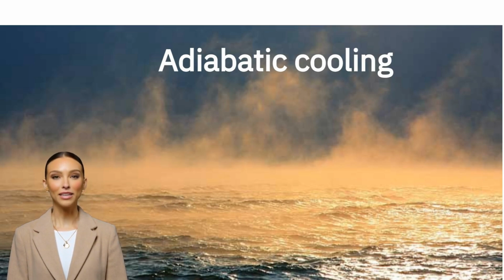Today, I will explain the principle of adiabatic cooling, which uses a natural phenomenon similar to the effect we feel near a lake or by the sea. You'll probably agree with me that the air near bodies of water is noticeably cooler thanks to the evaporation of water. This principle is the foundation of a technology that does not use chemical refrigerants or noisy compressors.